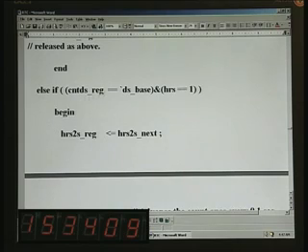And the next condition is the counter decisecond, we want 0.1 second. So when that is equal to the set value we have defined earlier, this one, and also the hours push button is 1, okay. So only if this condition is satisfied we need to increment the counter, right. That means we are incrementing every 0.1 second, okay. So 20 is what we have put earlier, just now we have seen 20 into 0.1 will be 2 seconds. So that is how you get that, okay.